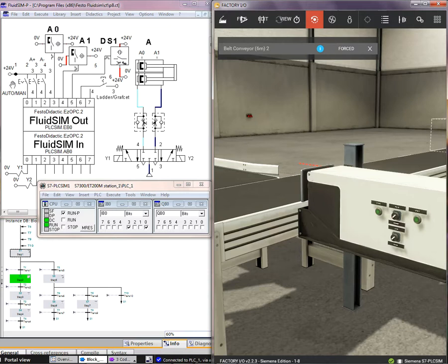You can see the push button auto manual connected to I0.0, push button S1 connected to I1 working as A+, push button S2 connected to I2 working as A-, and a proximity magnetic sensor connected to I3 as A0, mounted on the cylinder sheet at the end of the cylinder,